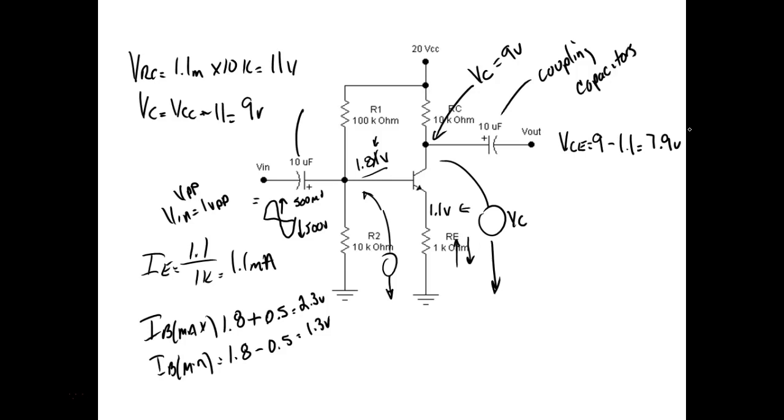That's what you consider. You calculate the resistors perfect, and then you choose the best standard value you can get, right? You understand? And then you screw around with it. So if it doesn't come up exactly, you would say, well, let's come up here and put a smaller resistor down here and see how it works. And that's the design of transistors. So you design it with math, then you choose standard resistors, and then you tweak it.